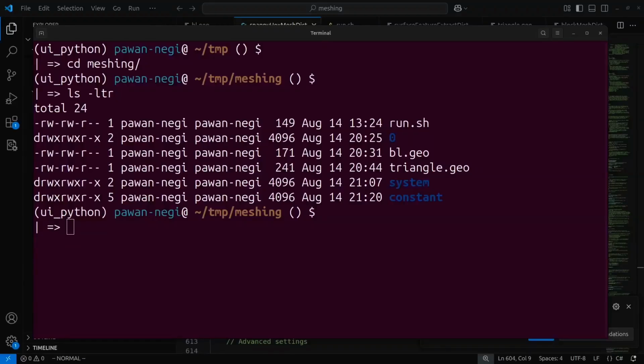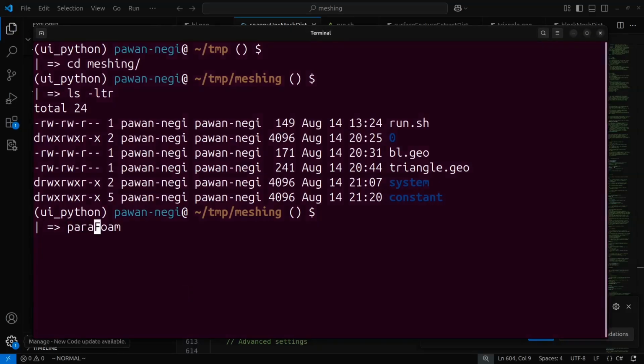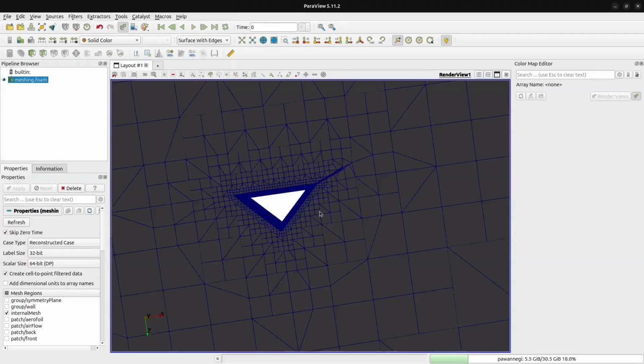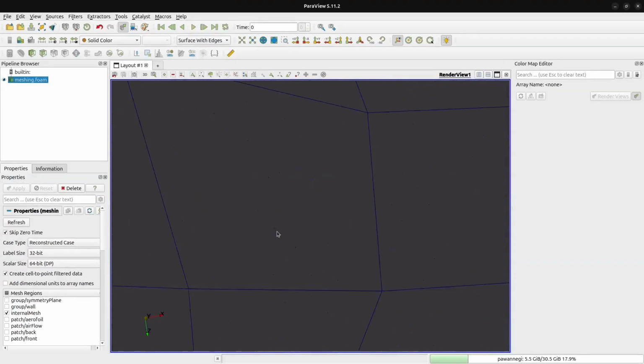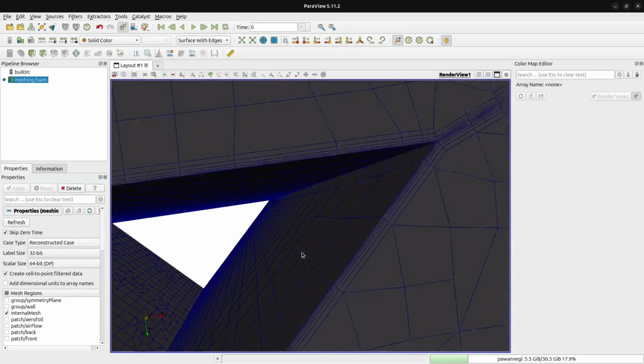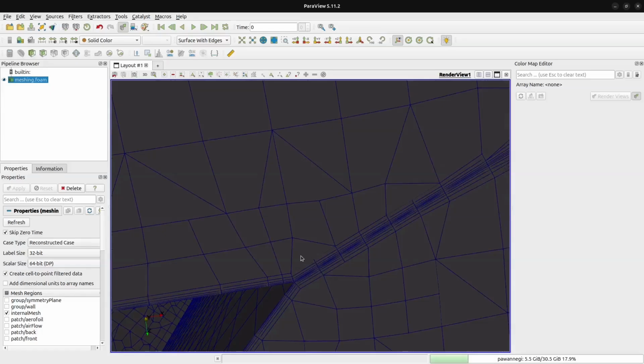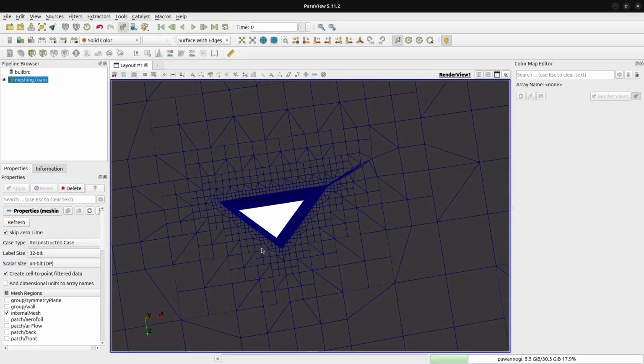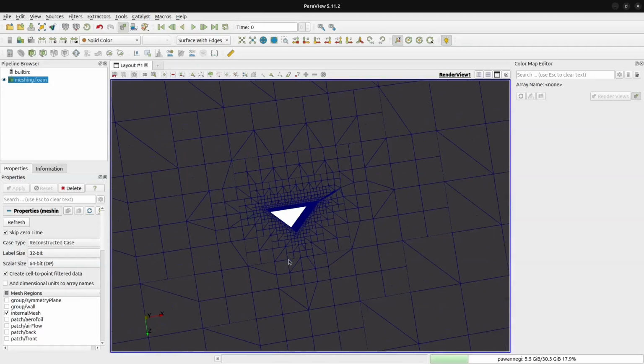Hello everyone, welcome back. In the last lecture, we tried meshing around this particular geometry, and we found that in order to have mesh layers around certain corners, we have to use internal faces and add layers on those internal faces in order to get layers to form around those corners as well. Now today we are going to try some more geometries of this shape, but with some large skewness as well as some high aspect ratio.